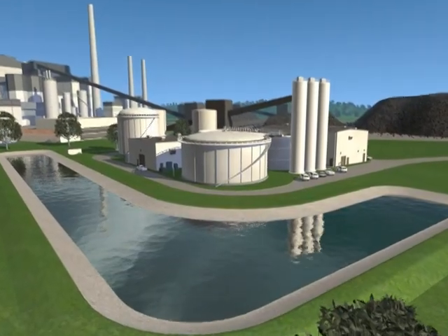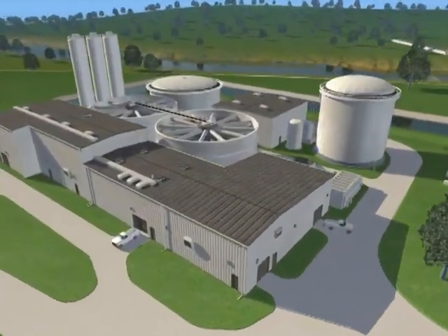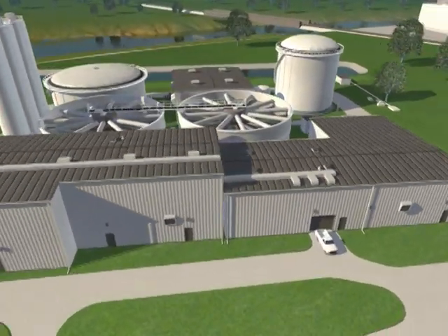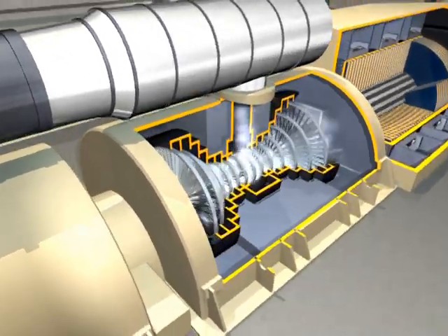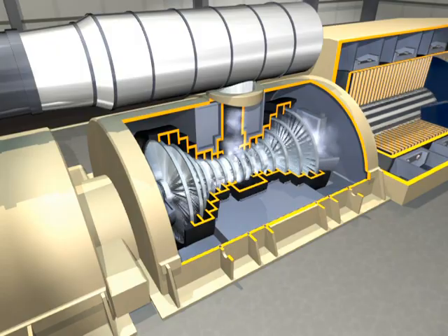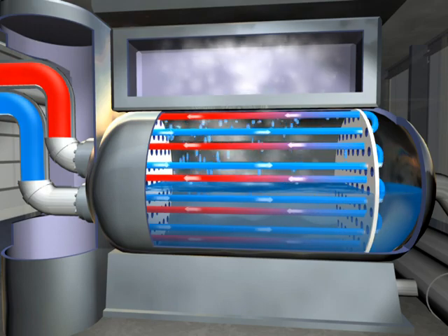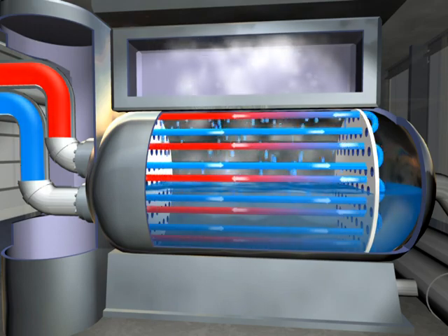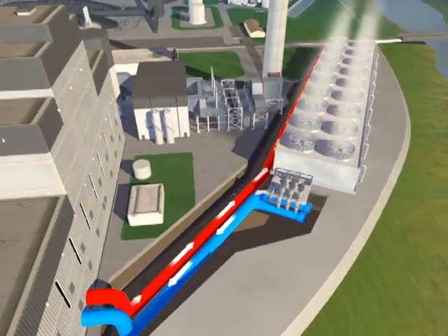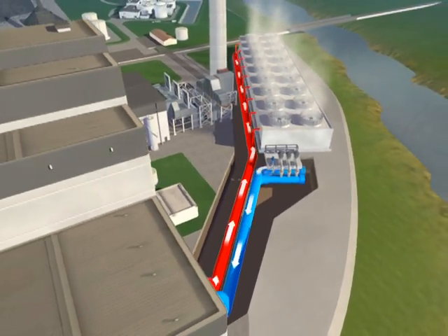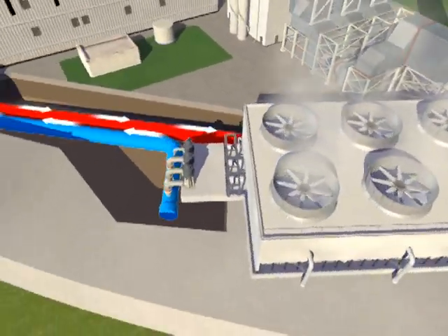The water that is heated into steam at coal-fueled power plants is called feed water. This water typically is supplied by wells and passes through a cleaning system to remove minerals and other impurities. After the feed water converts into steam and moves through the low-pressure turbine blades, it passes across tubes within the condenser that turn it back into water. These tubes contain cooler water from a separate circulating water supply. The circulating water constantly flows between the condenser and an external cooling tower. Fans and exposure to the air within the tower lower the temperature of the circulating water before it returns to the condenser.